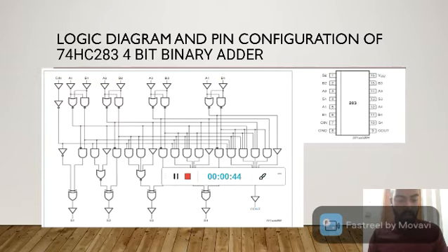The 74HC283 adds two 4-bit binary words A plus B plus the incoming carry CIN. The binary sum appears on the sum outputs S1 to S4 and the outgoing carry Cout according to an equation. Due to the symmetry of the binary add function, the 74HC283 can be used with either all active high operands (positive logic) or all active low operands.